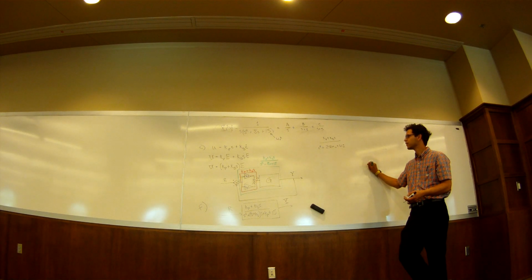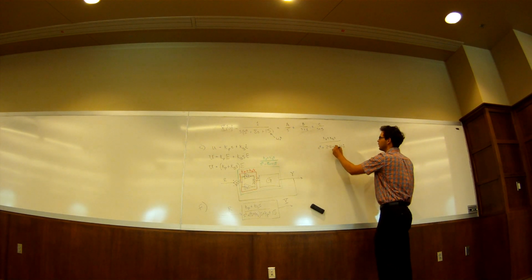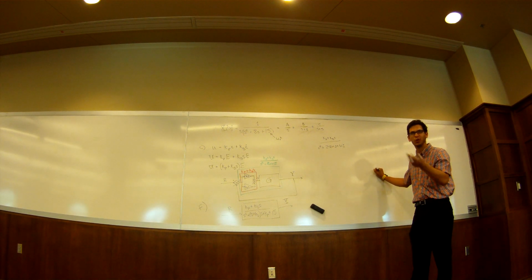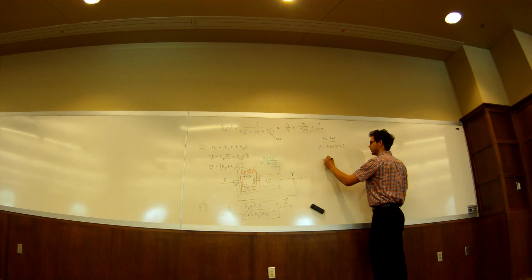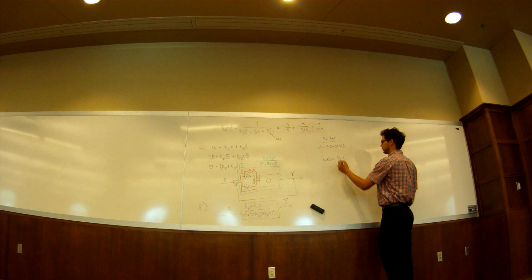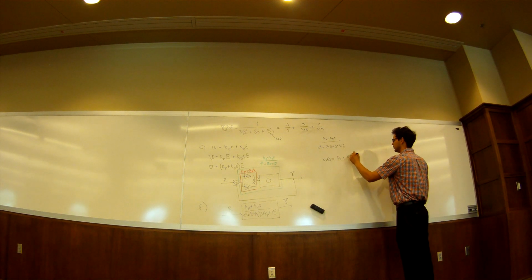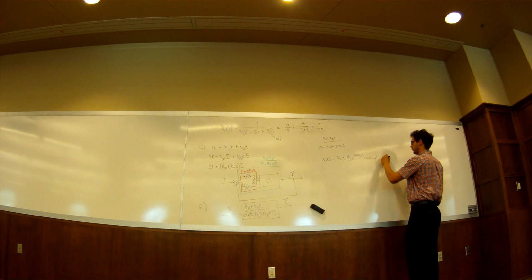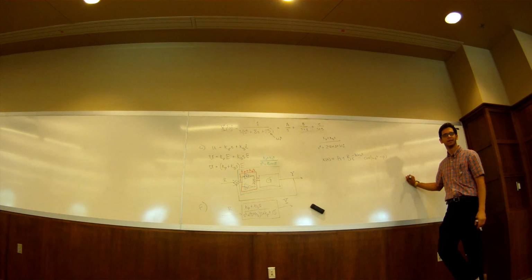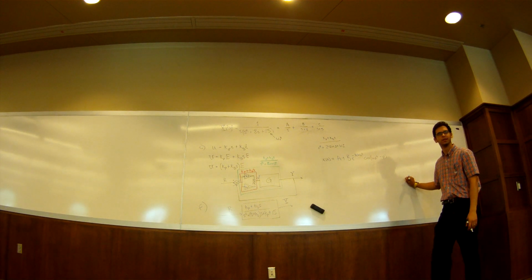Stefan? The second term is the denominator. So what would you write? I left it blank. You left it blank. I want a time response equation. You could say A plus B e to the negative zeta omega n t cosine of omega d t minus B. That's right. That's an acceptable answer.